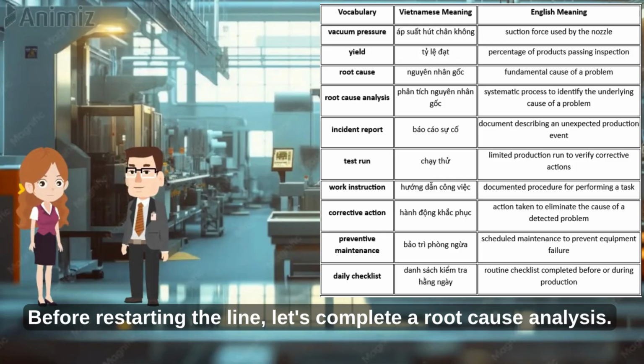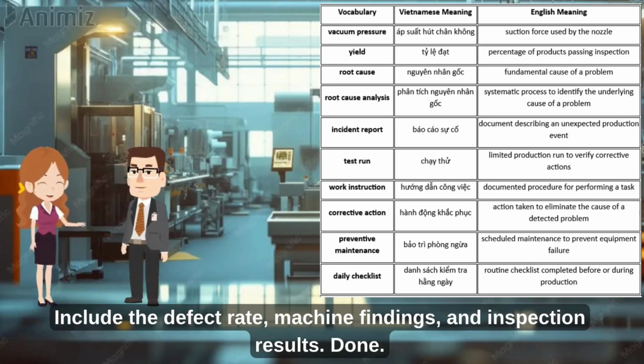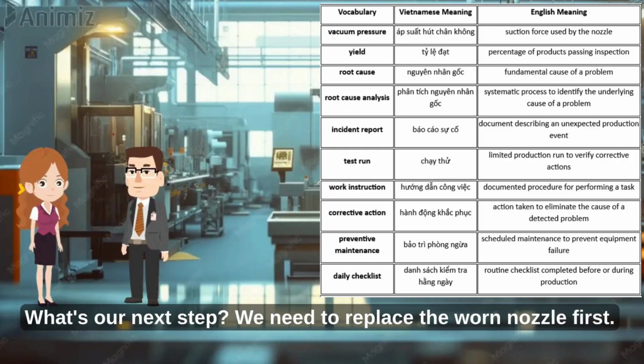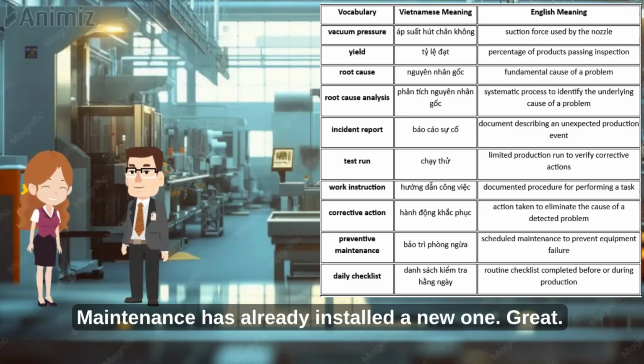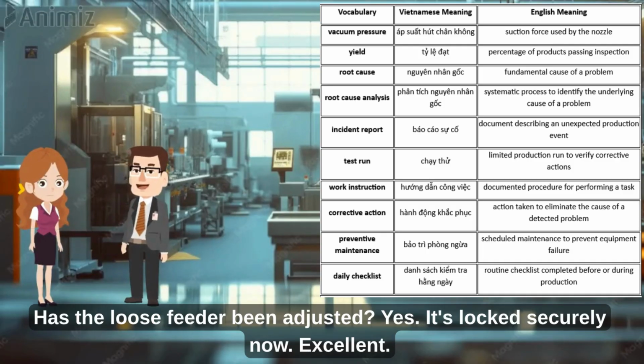Before restarting the line, let's complete a root cause analysis. I'll record everything in the incident report. Good. Include the defect rate, machine findings, and inspection results. Done. What's our next step? We need to replace the worn nozzle first. Maintenance has already installed a new one. Great. Has the loose feeder been adjusted? Yes, it's locked securely now.